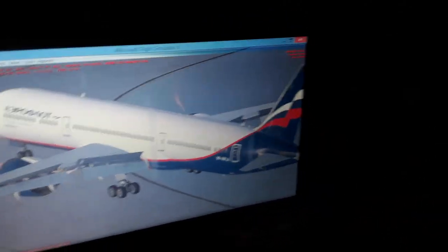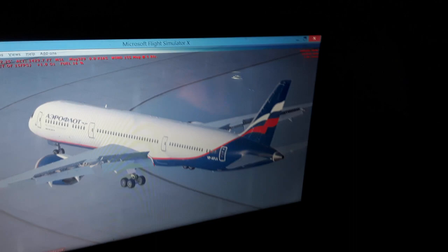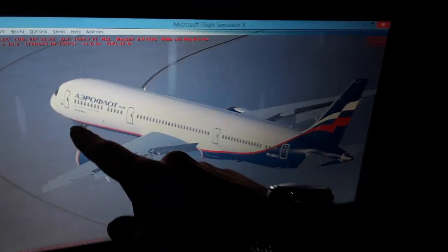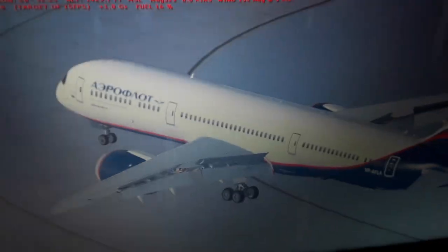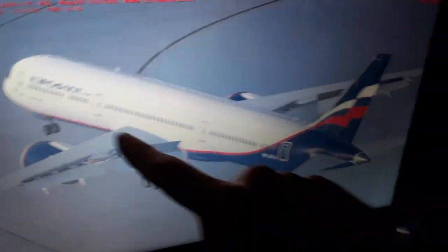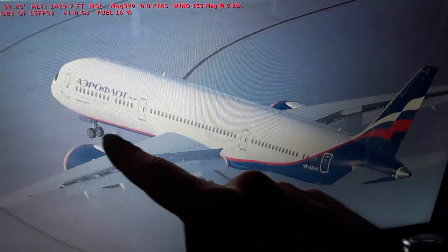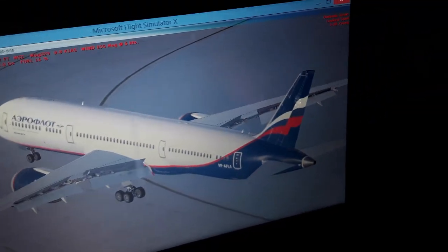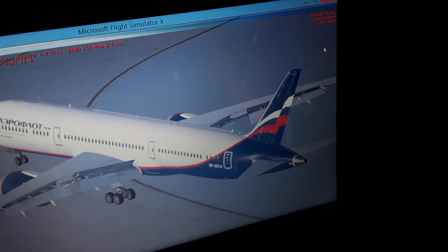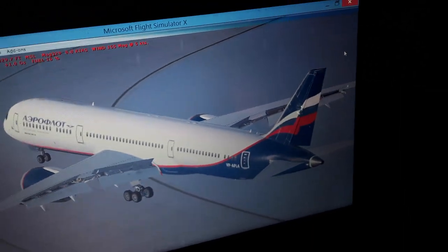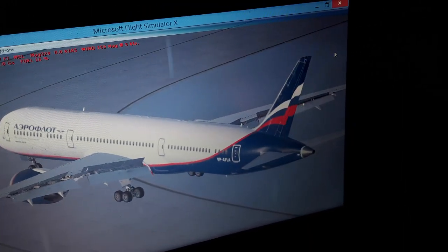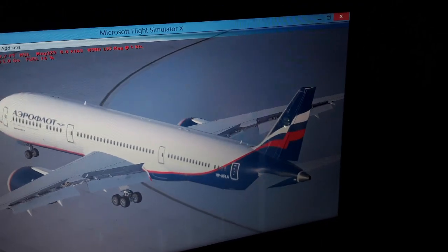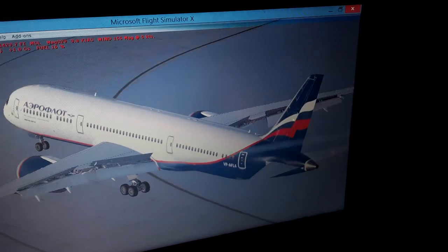Then as you increase your airspeed above 80 knots, or 144 kilometers an hour, in takeoff, the nose will be locked to zero deflection by the computer automatically, or a small deflection like half or 1 degree. So above 250 kilometers an hour in takeoff or in landing, you have only the rudder for control, like 140 nautical miles per hour, 140, 150 knots, or 250 kilometers an hour.